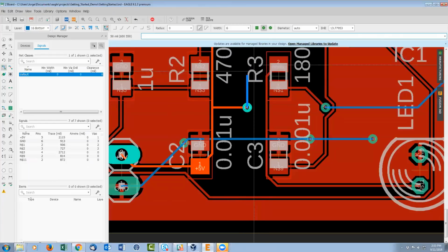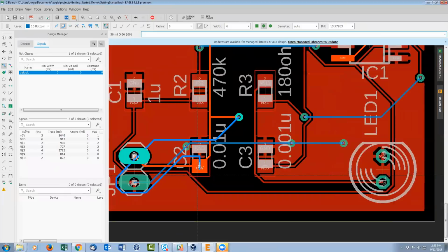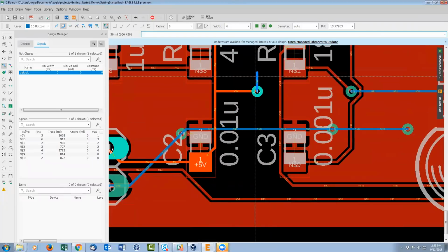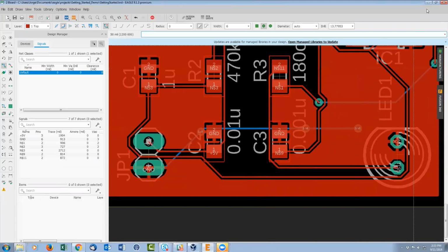Okay. And if you have a 4 or 6 layer setup for your board, just continue hitting the space bar. If you have blind and buried vias assigned, you continue hitting the space bar to cycle through all the options that you have for vias. Mm-hmm. And at the bottom, we can't see it now because the way my screen is scaled is kind of messed up. But at the bottom, you'll actually see some text telling you what layer it's going to go to. Yeah, at the bottom status bar, when the via is actually placed, it will let you know what layer the trace, if you draw a trace from that point on, is going to be on.